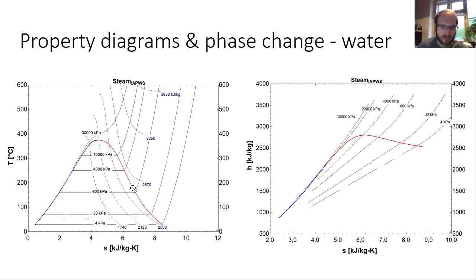Then, illustratively, you can see here lines of constant enthalpy, the dashed blue lines, which further in the right in the superheated fluid become nearly horizontal, because there the behavior is close to the ideal gas, where the enthalpy is a function only of the temperature. And compression, pumping or expansion for ideal change is the isentrope. Those would be vertical lines in this diagram.